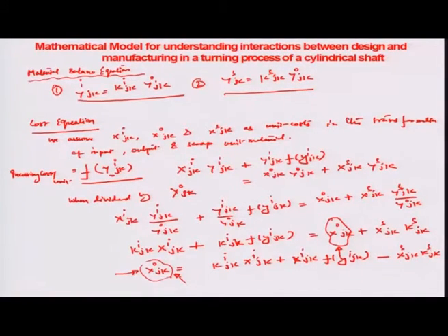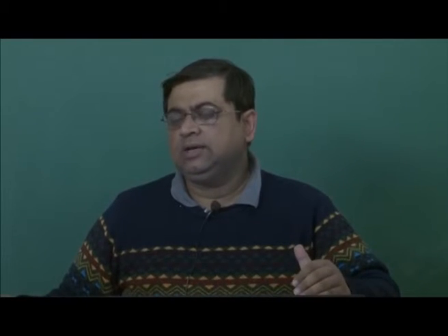Okay. There are other factors also which are important. For example, in this case, if there are a variety of capabilities of machines which are there, I should be able to find out which machine produces more or generates more waste and may induce a quality problem, or it can also give you an idea about, supposing there is a manufacturing lead time associated with each product, the ratio between the output and the scrap would be deterministic of what is going to be the extra time that is needed if you produce on one machine vis-a-vis the other. So, all these decisions, or all these parametrics based on the business environment, could be looked at very easily to take a realistic decision.